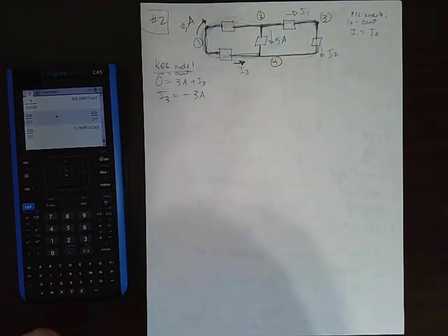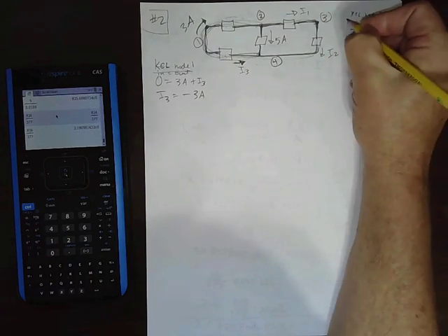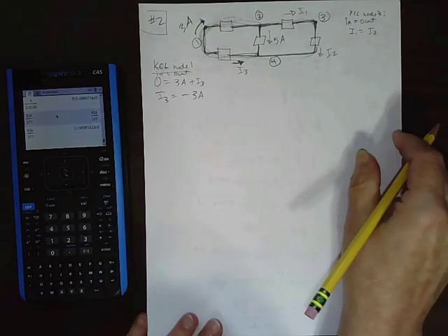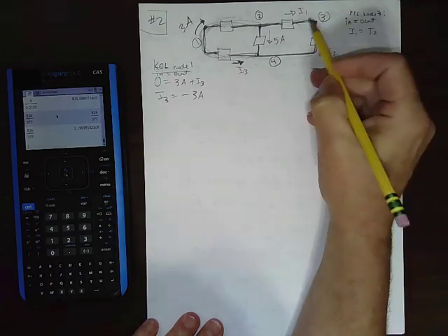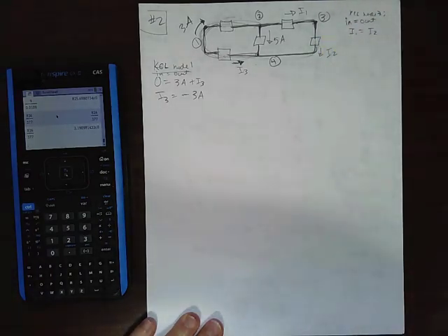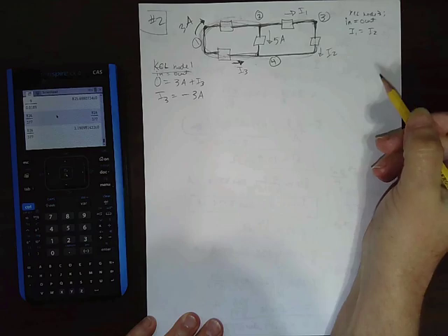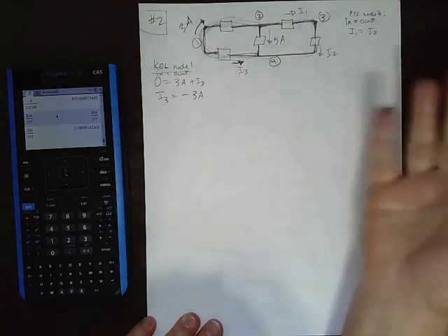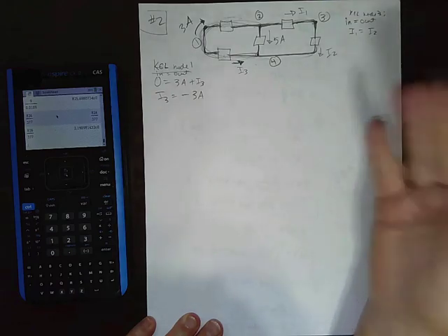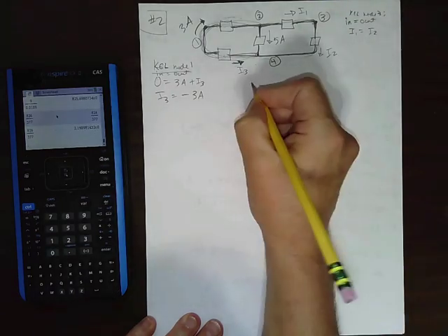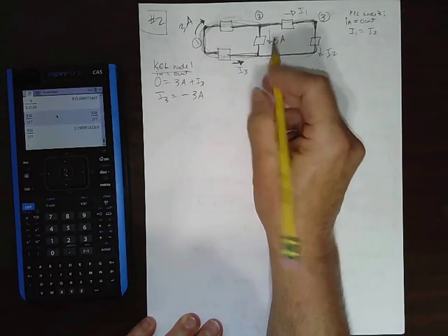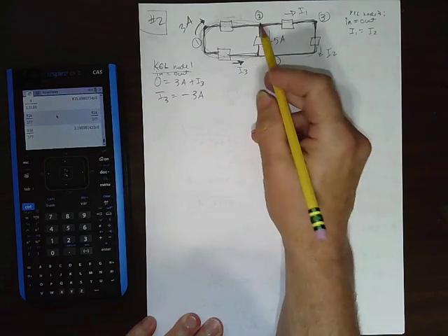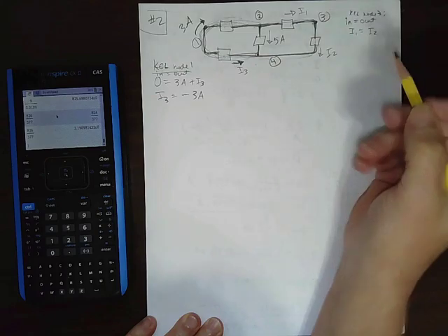Okay? So, maybe for this module, go ahead and write KCL at these nodes, or at least write down the equation from looking at this node. But, as we go through the semester, if we see something like this, hopefully we'll just be able to identify, oh yeah, those are the same current. Maybe one's negative of each other, but we got it. Okay, so let's do one more case. And so once we've got that, maybe we'll see that nodes 2 and 4 aren't going to give us any different information.